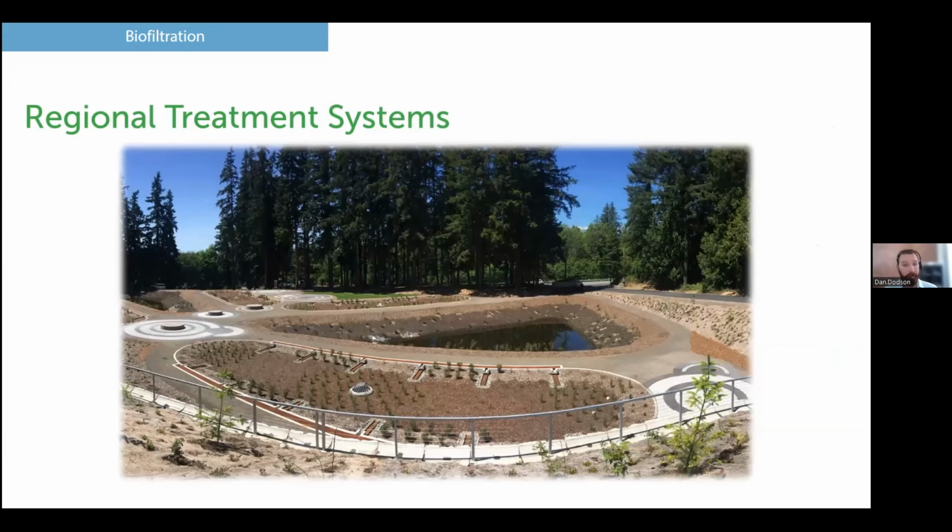And finally, one other application, you heard Veiko mention it at the end of his portion, is that these systems can be used in regional treatment areas. The increased capabilities with the high flow rates allow for drastically reduced footprints for the big regional treatment systems. With the engineered media, your reduction of your footprint is up to 90% versus the traditional practices, because we've got that 10 times multiplier in flow rates that we discussed in the beginning.